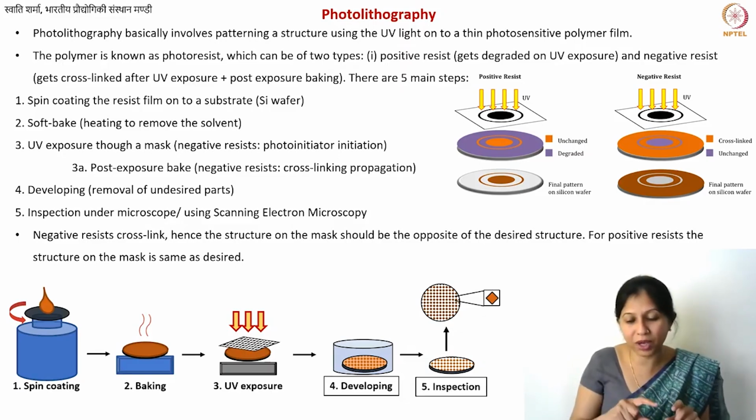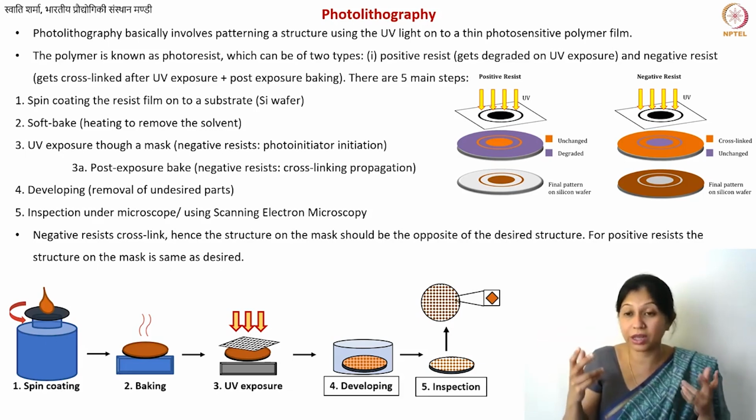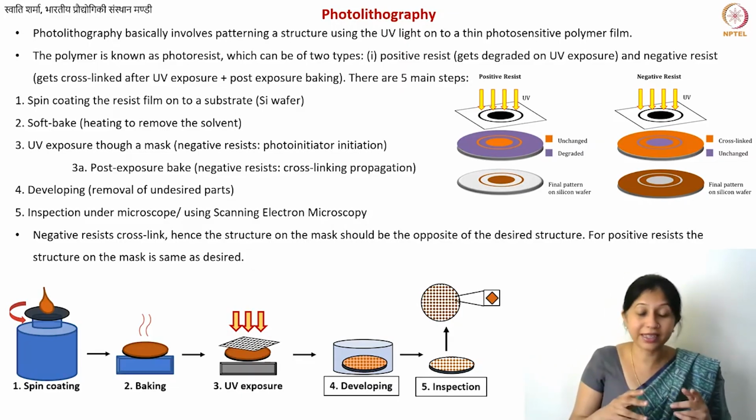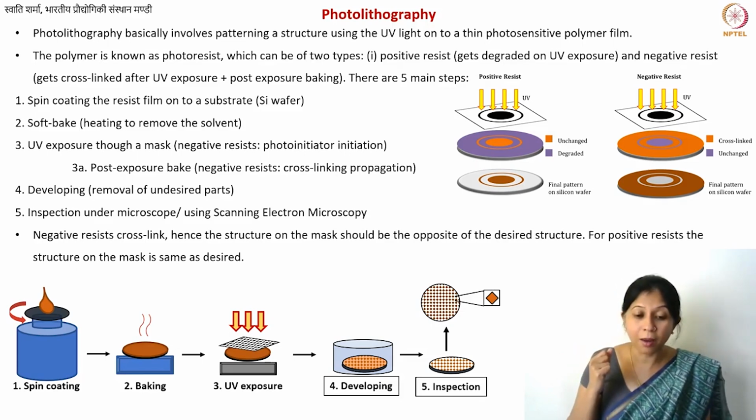And in some cases, if you keep on heating, let's say if I heat it to 3000, these turbostratic sheets, not the curved carbon parts, but the turbostratic part, do have a possibility to convert into graphite or to become more graphitic, which would give you slightly higher electrical conductivity, maybe also better mechanical properties. But why don't we do it?